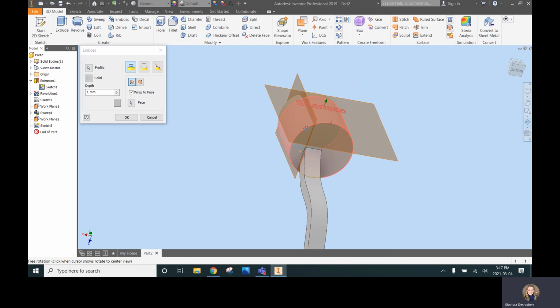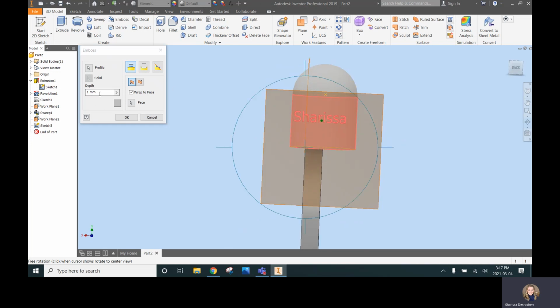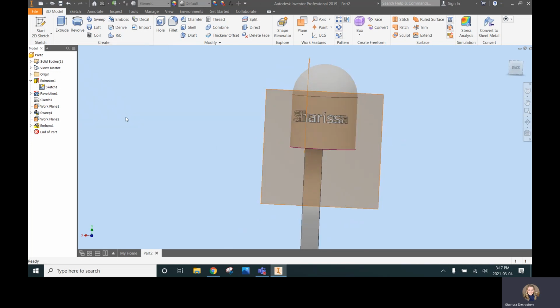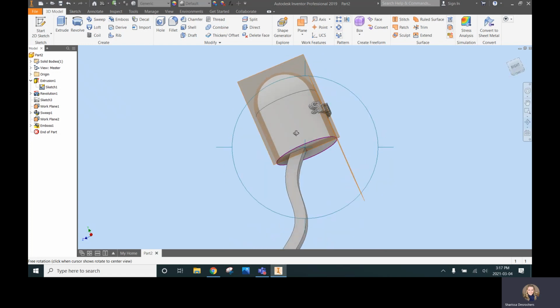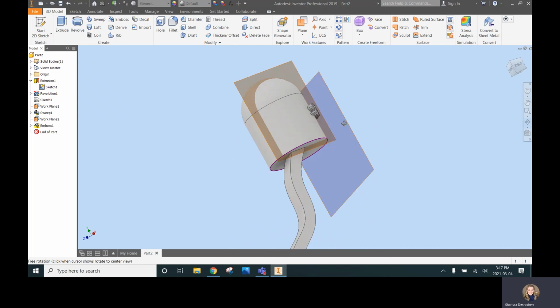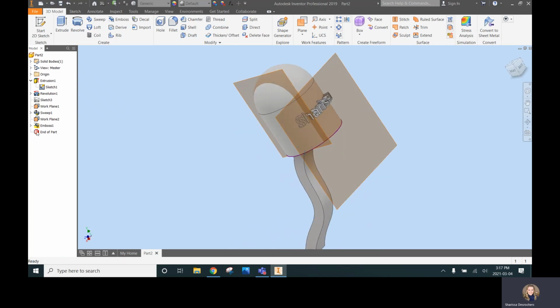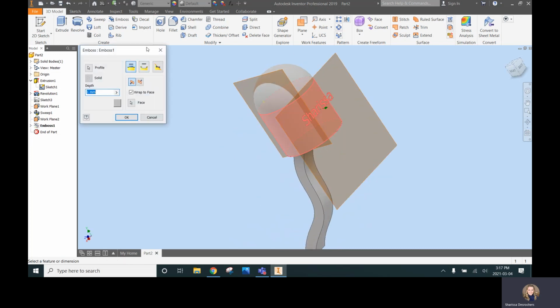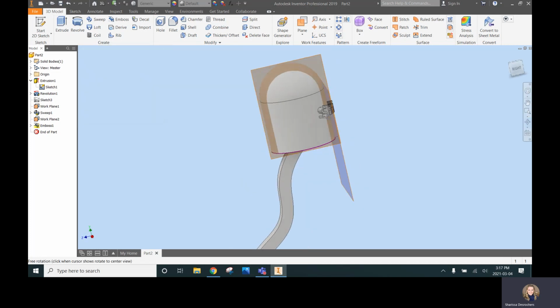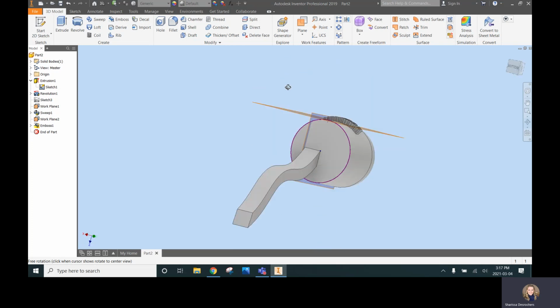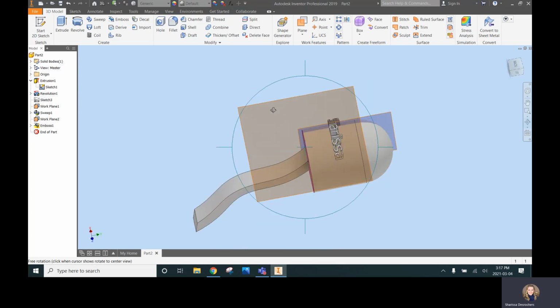So I want it to wrap to that face and then come out a depth of a millimeter. Okay. And we'll see. There we go. So here what it's done is kind of like an extrusion style. You can also go the other direction and have your name go in, but this way it comes out. So again, if you wanted to emboss, you could also go the other direction, like that. So that's how you would wrap text.